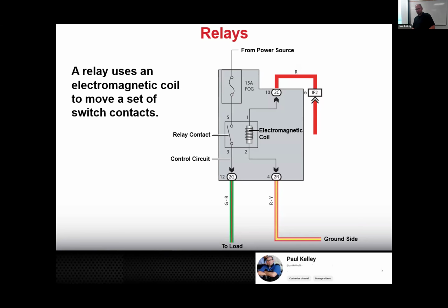So we're building this understanding again to the point where you can actually diagnose why the thing doesn't work, whatever the thing is. In this case, we talk about the pump, but really it was the fog lamps, right? If the fog lamps don't work, it could have 2 bad fog lamp bulbs, but probably not. So you'd probably do a lot of your troubleshooting right here at the relay. And if you wanted to be really down and dirty, one of the things I would do is actually just put my hand on the relay and have somebody turn the fog lamp switch on and off. And do you know what I'd be feeling for? Heat's one thing, but I want something a little more audible. I want to hear or feel the click.